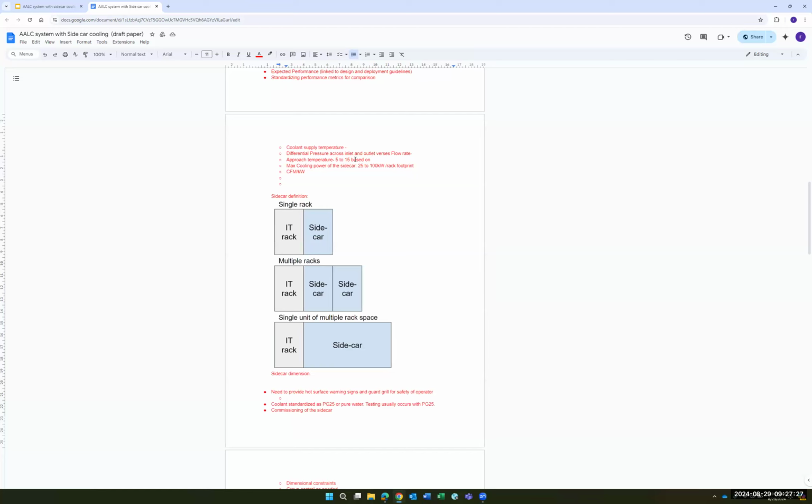I see. That's why I'm giving a range here in terms of the cooling efficiencies and also the chip temperatures. I think it is something between, per rack, I mean sidecar, something between 40 and 70 kilowatts per rack per 10 Kelvin approach will be something normal.